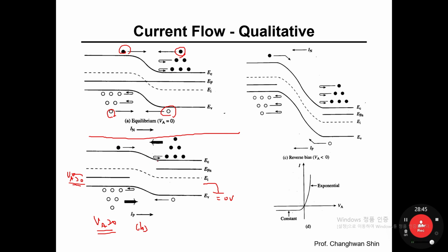Qualitatively, not quantitatively. We're going to tackle quantitative analysis sooner or later, but here, take a look at what kind of things would occur. Here, the built-in potential, qVbi, minus VA. So depending on how much forward bias has been applied, the energy barrier height from the perspective of electrons in the n side becomes lower and lower. Originally only hot electrons would move into the p side, but now, because of the lowered potential energy barrier height, many electrons are ready to move into the p side.